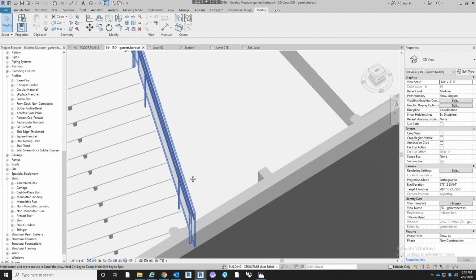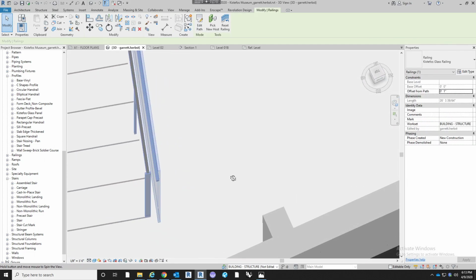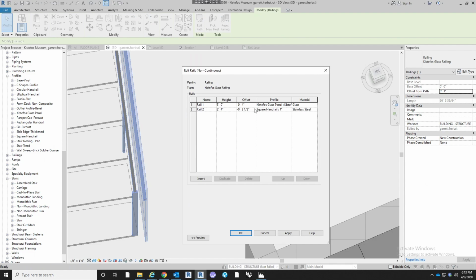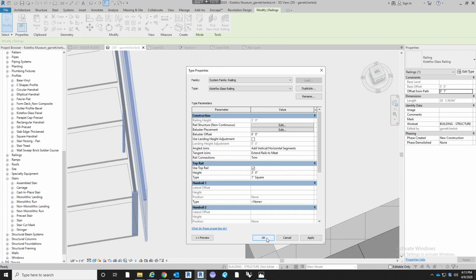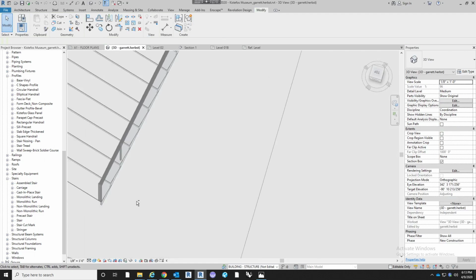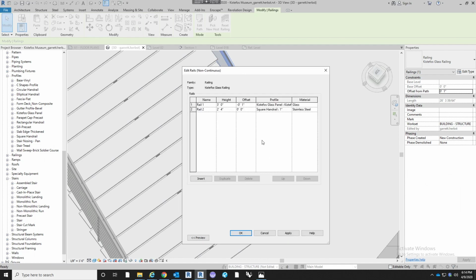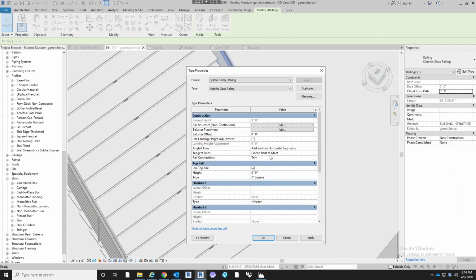And then the one thing we still need to do, these are hanging off right now. So let's bring this in a little bit more. Let's only offset the rails. Let's only offset that -1 inch. Negative, looks like 0. Let's see what that looks like. 0 inches for the square and -1 for the glass. That looks better. Let's do -1.5 inch. Actually, let's just do -2. -1 inch. And then we need to change that for the rest of these as well.